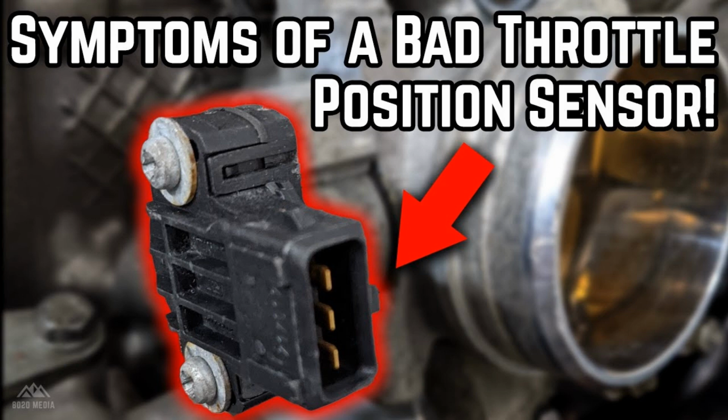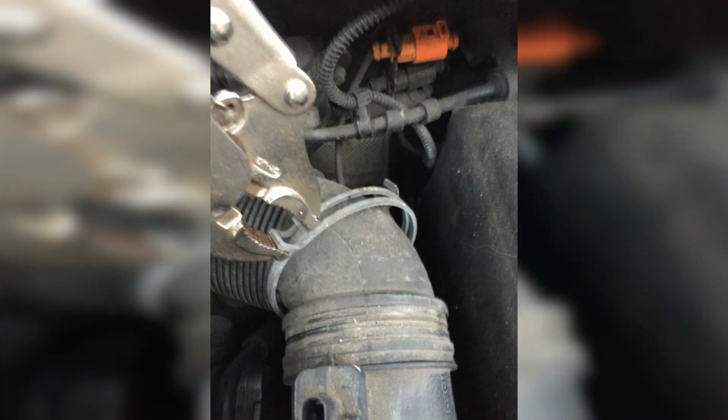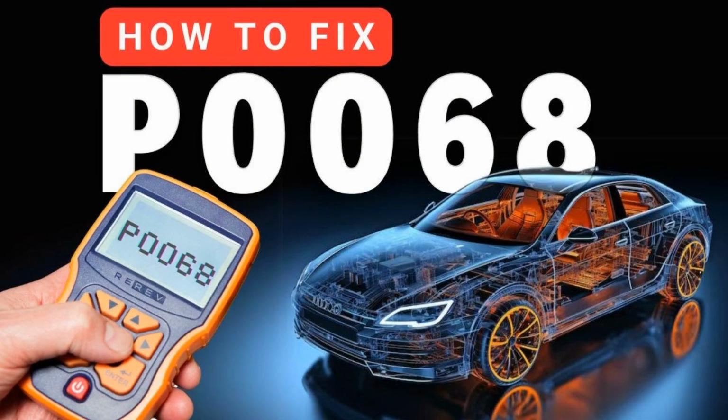What are the common symptoms of code P0068? If one or more of these sensors send inaccurate signals to the PCM, the computer may send the wrong amount of fuel or activate the ignition system at the wrong time. An affected vehicle will display the following warning signs related to code P0068: check engine light, rough engine performance, irregular idling or poor acceleration, and increased fuel consumption. The PCM can also set other codes associated with whatever developed the problem. For example, a faulty MAF sensor may trigger a P1101 code along with a P0068.